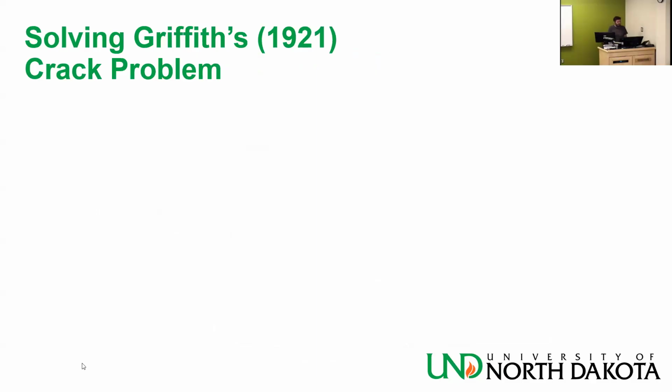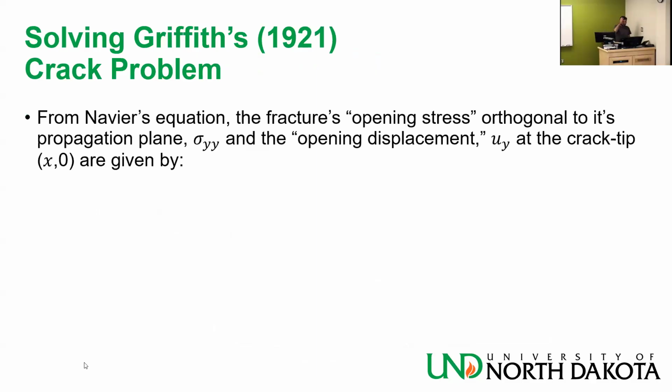Now, solving Griffith's crack problem, from Navier's equation, the fracture's opening stress orthogonal to its propagation plane, sigma yy, and the opening displacement uy at the crack tip are given by the following.